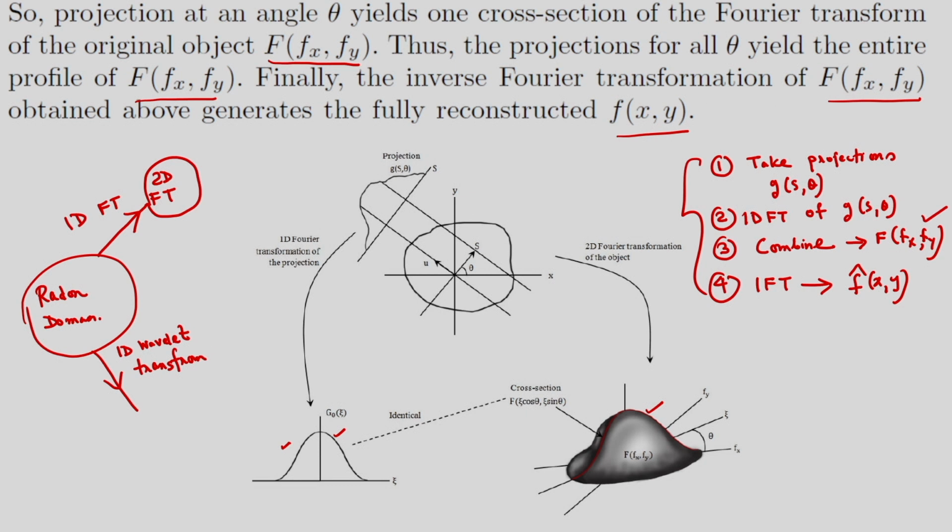So, with the 1D wavelet transform, this transformation is a very important transformation, the Ridgelet transformation. So, how to get the Ridgelet transform? First I have to determine the Radon transform, and after this I have to consider the 1D wavelet transform, then in this case I will be getting the Ridgelet transform. So, one is the 2D Fourier transform, another one is the Ridgelet transform I will be getting.